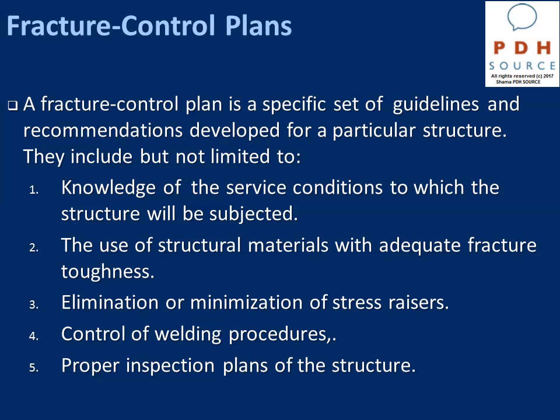These guidelines, actions, and recommendations should eliminate or minimize stress raisers in the design. We know that stress raisers in the form of flaws or sharp corners, scratches or notches are able to amplify the applied stress, and if we can avoid them, it would be better for design and for the health of the structure.